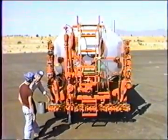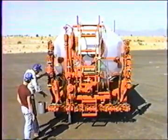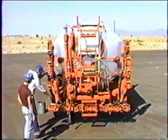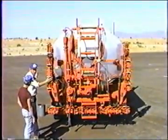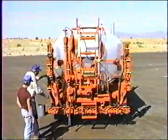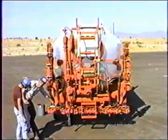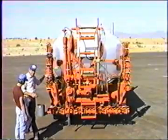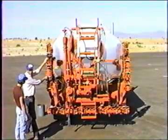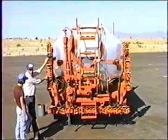These equalizer valves, the swing joint equalizers, have opened up. Now it can feed the main bar direct from the swing joint without it having to go out through the wings first. We're feeding the main bar direct. Also, because this equalizer valve and the one on the other side are opened, now it can actually feed the wing through both passages, both the internal passage and the external passage.